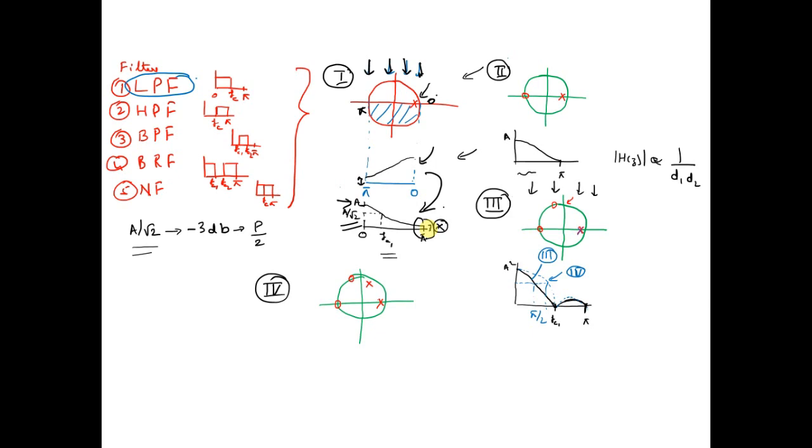Hence, to stop that phenomenon, in many cases what we do is apply a zero at pi while designing the low pass filter. So what it will do? It would be similar. You will be having some gain over here, A. Now remember, this gain A is dependent both on the pole and the zero. You have to find out both the things. In the previous case, it was only the distance of the pole to the frequency component.